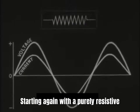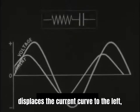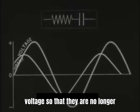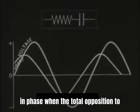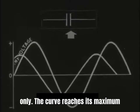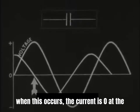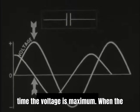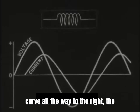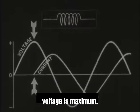Starting again with a purely resistive circuit, capacitive reactance is substituted for resistance. This displaces the current curve to the left, showing that the current now leads the voltage, so that they're no longer in phase. When the total opposition to current flow becomes capacitive reactance only, the curve reaches its maximum displacement to the left. Notice that when this occurs, the current is zero at the time the voltage is maximum. When the maximum inductive reactance is placed in the circuit and displaces the current curve all the way to the right, the current is also zero at the time the voltage is maximum.